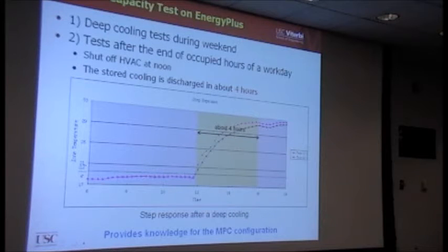Position, we have to do some testing. This is also what you need to do for a real building. That is how fast or how slow your building structure can release the heat, or it's the negative heat actually that you store to pre-cool the building. If it's released entirely within 5 minutes, then you cannot shift much of the peak load. Okay, if it's released within a window of 4 hours, 5 hours, that means you could perhaps shift it by 3 to 4 hours and so on.